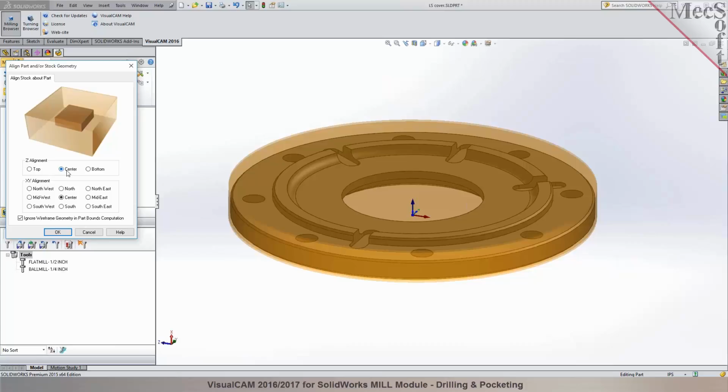So we would then establish the origin. Since your part is 0.875 thick and the stock is 1 inch, do you want to leave material at the bottom, or do you want to remove the material off the top when you're doing a facing operation, to bring it down to the actual thickness of the part? We'll have to face both. You'd like to face both sides? Yes.